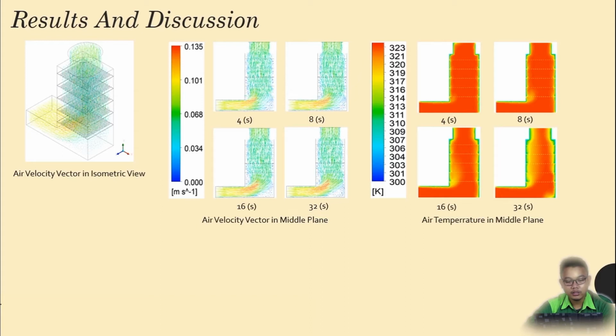In position x equals 0.6 meter to x equals 1.2 meter and y equals 0 meter to y equals 1.33 meter, the air velocity was rather low. It is because of gravity acceleration, and there are several trays inside the cabinet. The trays became a disturbance for air to go up. It was signed by a green color vector. The airflow near the wall had a blue color vector. It means low air velocity, because the wall had a temperature the same as the ambient temperature.